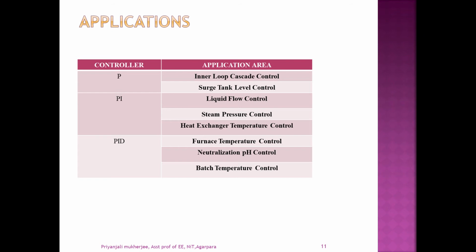So only P control is suited for many cascaded applications as it provides an effective means for counteracting upstream process disturbances. Within the cascade architecture, the controller output of the outer loop serves as the set point of the inner loop. The inner loop is able to see and react to disturbances ahead of the outer loop, and when tuned using only the P configuration, the controller is able to react faster than the outer loop and thereby check the brunt of disturbances. While overshoot can be expected, its impact is confined to the inner loop.